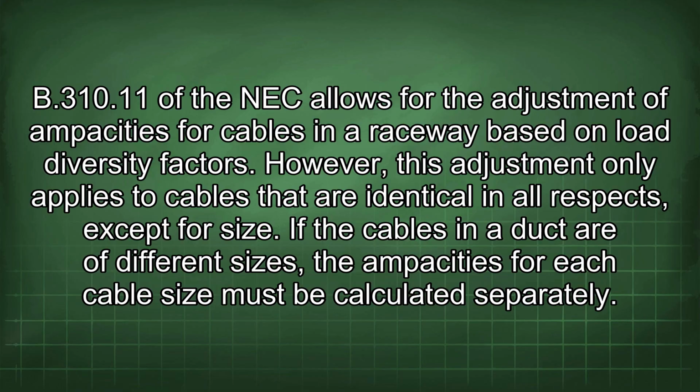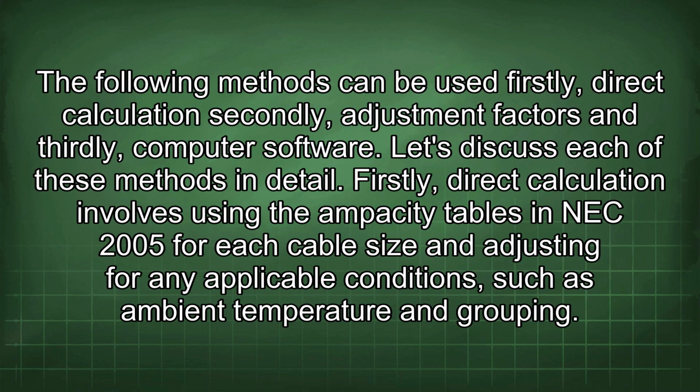If the cables in a duct are of different sizes, the ampacities for each cable size must be calculated separately. The following methods can be used: firstly, direct calculation; secondly, adjustment factors; and thirdly, computer software. Let's discuss each of these methods in detail.